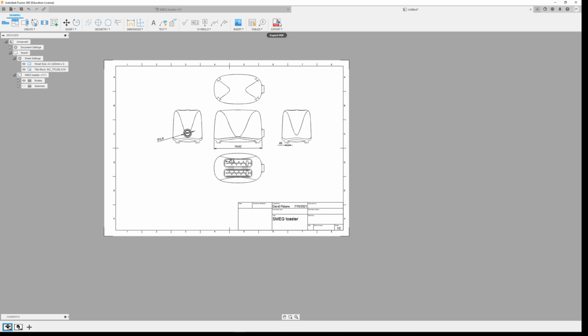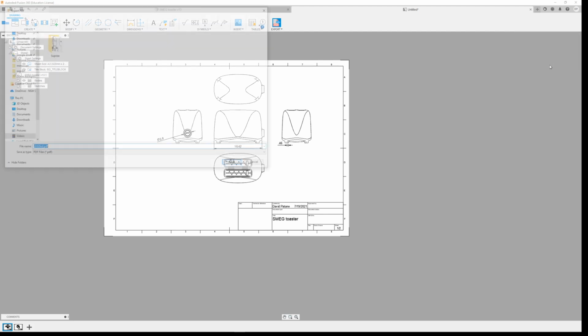You can export it as a PDF, or you can also export it as a drawing file. So that could be pasted into like a Word doc. Actually, both of these could be. You can export as an SVG, which is like the X and Y coordinates, I believe, of everything. You can also export it as a DXF. I think you're going to be basically doing yours as a PDF or a drawing, but let's say export it as a PDF. All sheets, press OK.